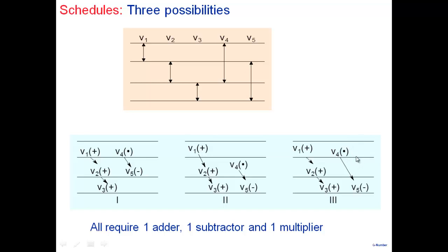So will the clock cycle be the same? Well, if I look at it, note the result of the multiplication is required in the next stage, right? So how much should the clock cycle be? The clock cycle time period should be at least equal to the time taken for multiplication to occur.